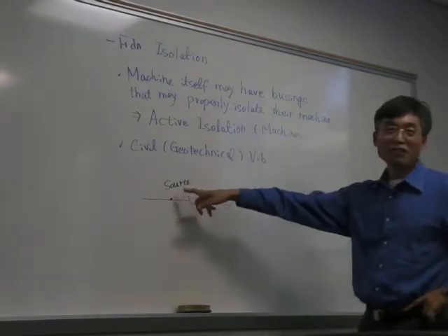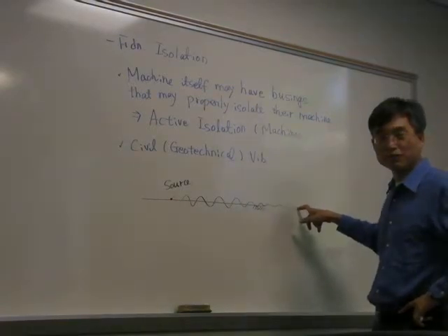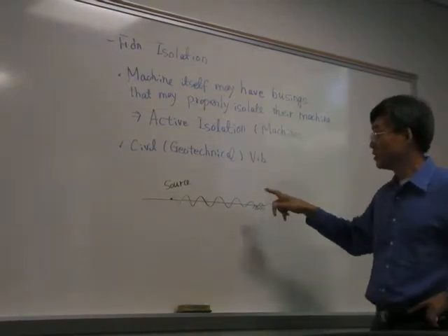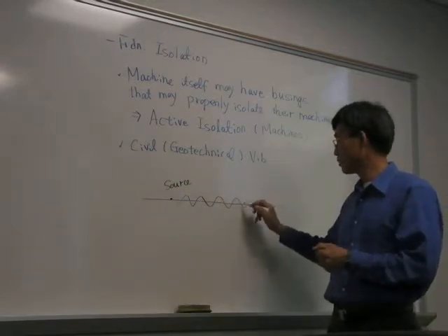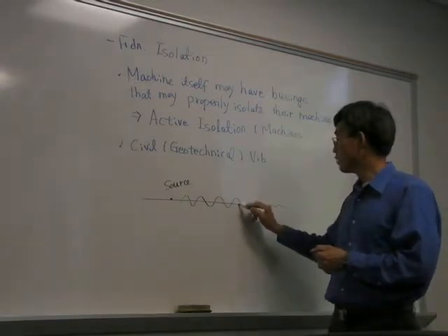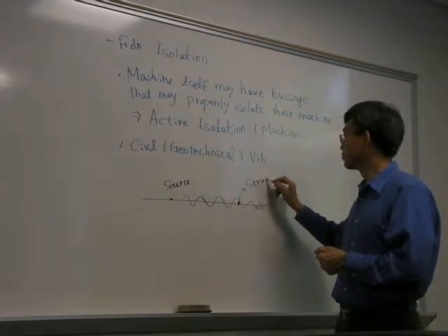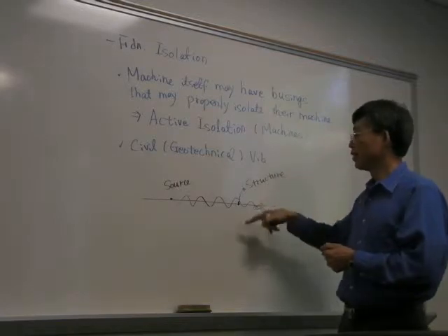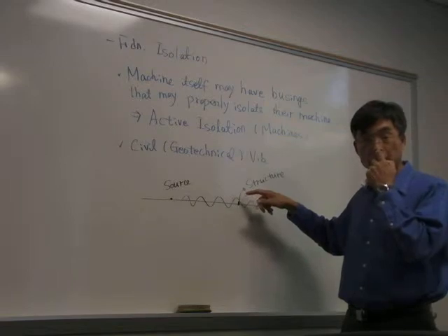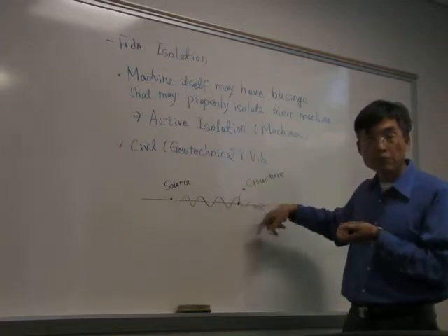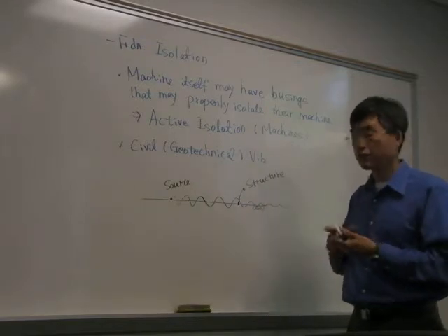We know that when we have a vibration source, it will gradually die out. But when the distance from the source to, let's say, some structure is close, let's say our structure is here, the amplitude of the vibration may still be quite severe. Again, when we talk about amplitude of the vibration, that is related to the particle velocity.